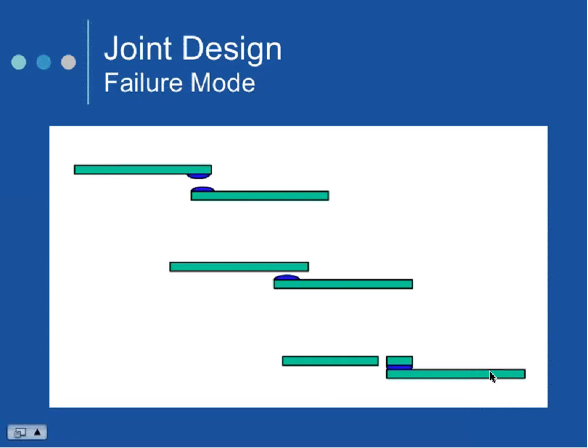So in this first case, does anybody know what the failure mode would be called there? Cohesive. Exactly. And what that means is, and you saw that with the metal-to-metal adhesive on either part, in gasketing that I showed you way back in the beginning, the adhesive failed. It doesn't have enough cohesive strength or enough integrity to really give you that kind of bond. I've had that one time in 30 years with the company. So in the medical world, we don't see that very often. In industrial, you may see that because, again, sometimes you want that in a gasketing application. The second one is going to be a problem.